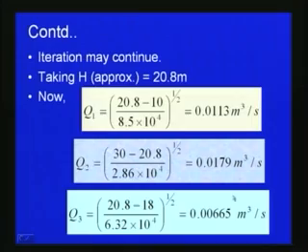So like this, for the branching pipe system, as we discussed, we can write the energy equation, use the continuity equation, and then solve these equations to find out the unknowns like the flow through each pipe, and also solve for the piezometric head. For example, here we found the piezometric head at the junction points. Like that we can solve different kinds of problems.